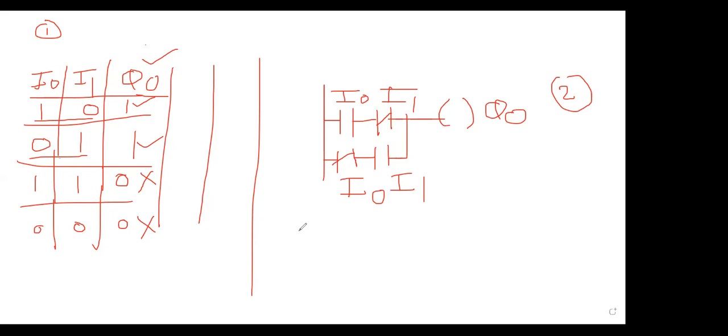So once more, I shall repeat and will give you one example. Make a truth table, go to the first output, take a coil. Check the true condition of output, add the status of all inputs. Don't skip any input. For input 1, you take NO. For input 0, you take NC.